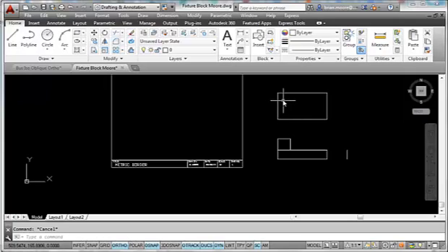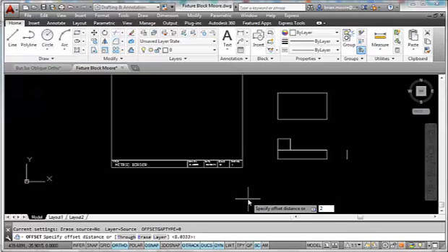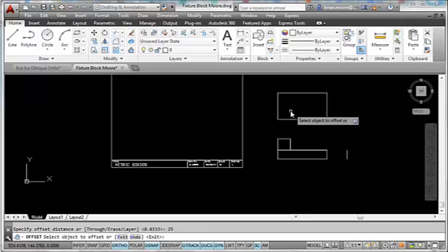Now I've got to draw the square on the top here. So what I'm going to do is, I know that it's 25 millimeters by 25 millimeters. So I'm going to offset 25. And then I can frame in the object that way as well. Okay. And now I'm going to trim, enter, enter, turns these into cutting edges.